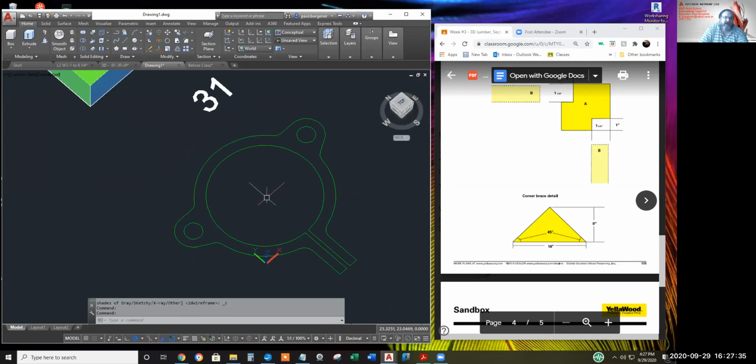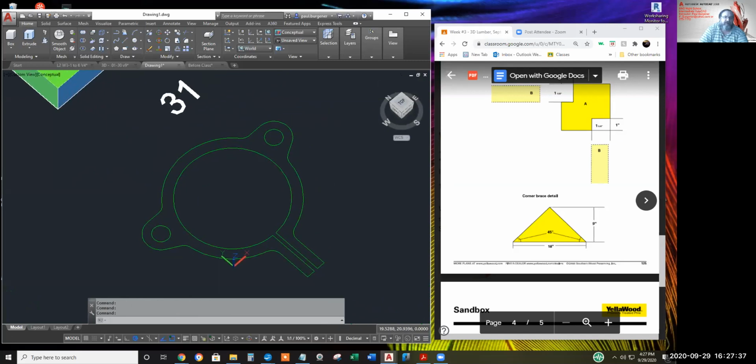Quickly doing the exact same procedure for item number 31 here. Again, probably the hard part's drawing all these lines and arcs in 2 dimensions. After that, it's pretty easy. Just p-edit, select one. Yes, I want to convert it into a polyline. Invoke the join option by any of the methods we learned in introductory to invoke options.